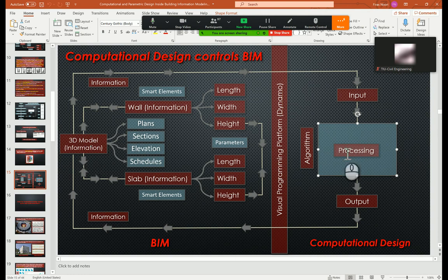If you need to make 200 or 3,000 elements of a stadium, which I'm going to show you in the next example, you're going to do that in a couple of seconds, not hours, not days, seconds, when you use the computational design platform. Send back the thing you want. Of course, you're not going to send 20,000 or 10,000 models to Revit. It's going to explode. Even the best computer will not take that, but you're going to compare the options you got and then send back to Revit to do it for you.